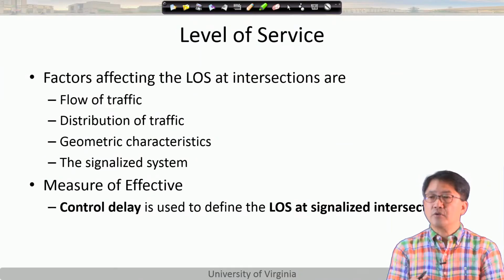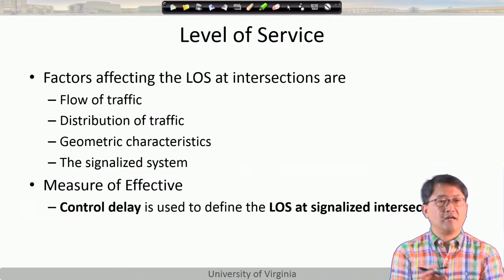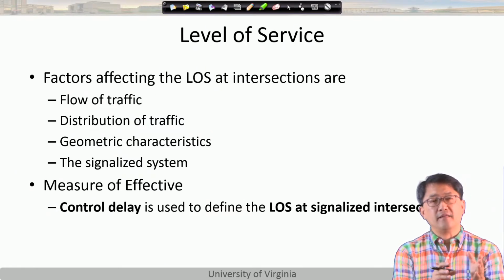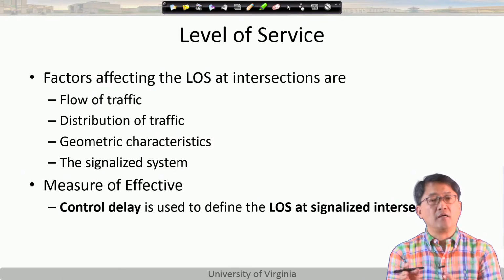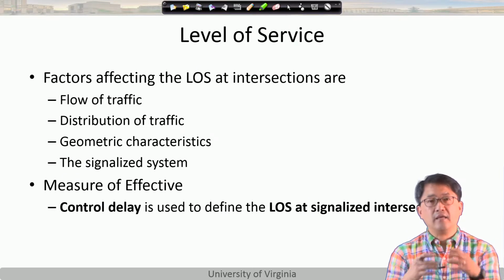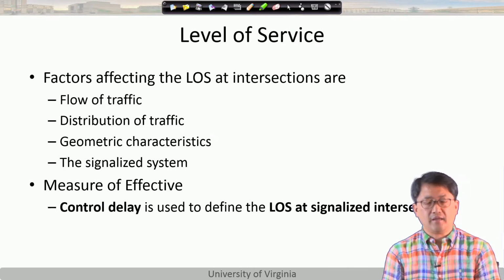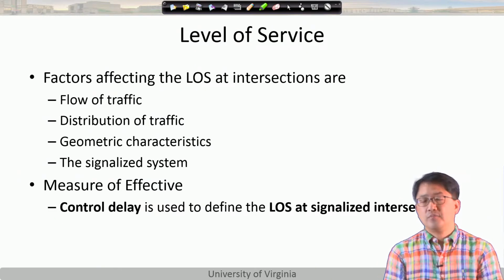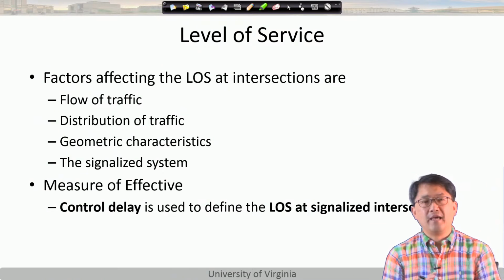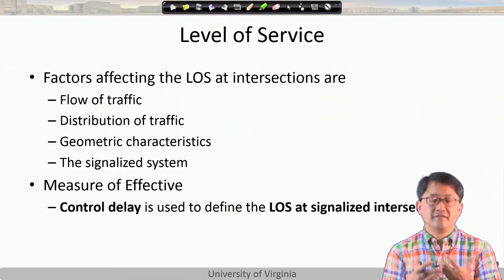And then they also realized that cars are interacting with each other. If you are on the leftmost lane and try to make a right turn, that's going to have interactions with other cars. And that's creating delays. Or a lot of lane changes cause an effect. So they include everything as control delay. And because of this, level of service F used to be 60 seconds per vehicle. Now they made it 80 seconds per vehicle. Again, this is a consensus.